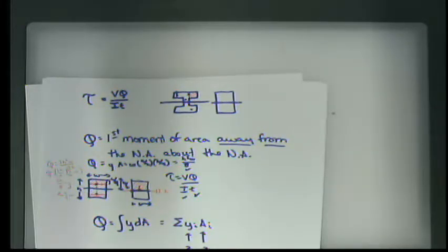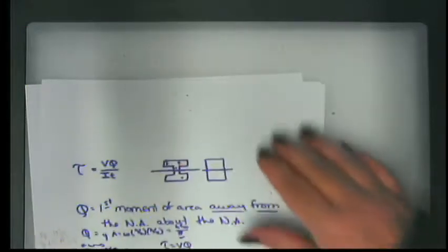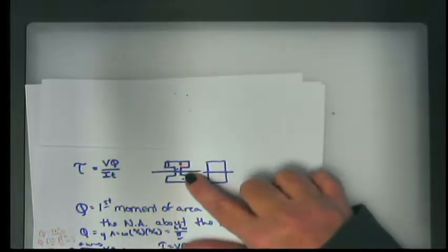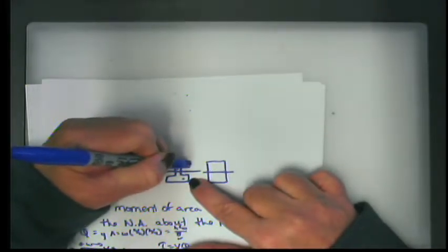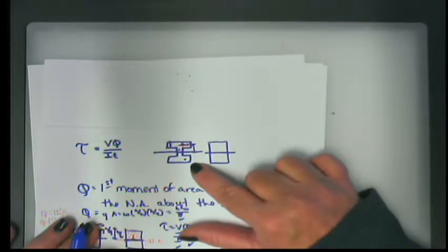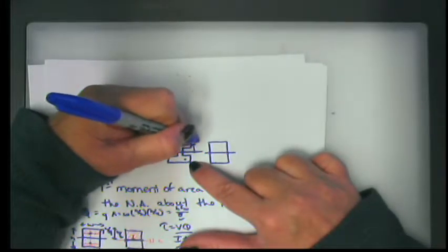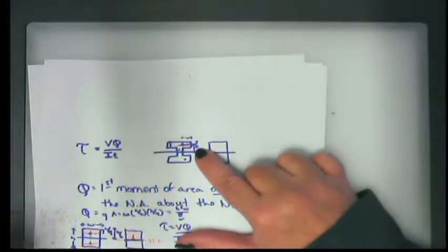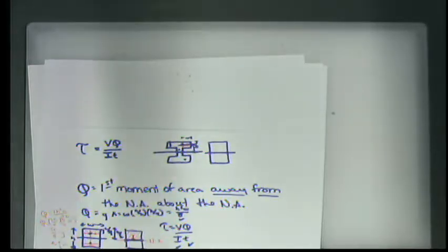So if we had that I-beam right there, where it's off in both parts, then do you take the flip of the x or do you take the flip of the y? No, the y bar is always in the y direction. So you find this chunk, you draw a line through its centroid, and there's your y value right there. There's just a gap. That's exactly right. And then this is your width, and this is your height. So the area is width times height, and your y bar is that dimension. Got it. Yeah, it's a good question.